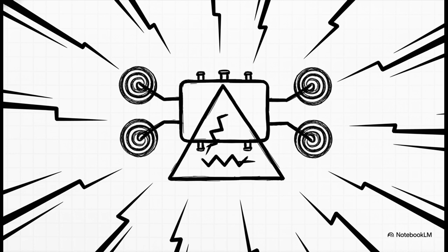If you encounter one of these, you can't just use a single series impedance. It won't work. You must extract and model three separate impedances between the winding pairs. If you model the wrong winding configuration or try to force a three-winding unit into a simple two-winding model, your voltage regulation studies will be silently, dangerously wrong.